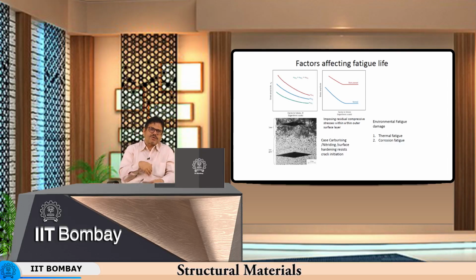So, the extent of indentation, the speed or the velocity of the balls, and the amount of energy that is transmitted into the workpiece for plastic deformation, all govern the depth of indentation that is made by the shot, and therefore the residual stresses being induced by this process on the surface.